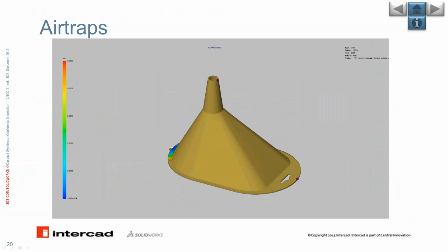So it's about air traps. Basically, in every mold design and part injection, when the flow is coming to the corners and the ends, there is existing air inside the mold and it needs to be vented.